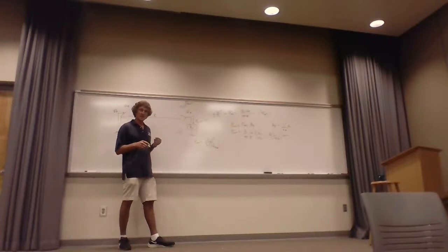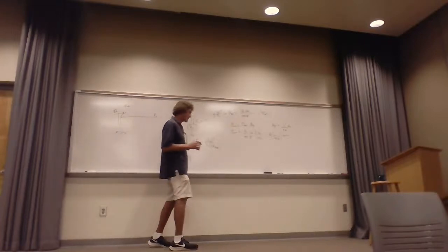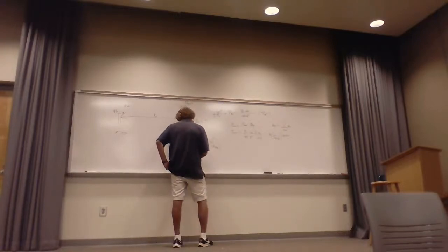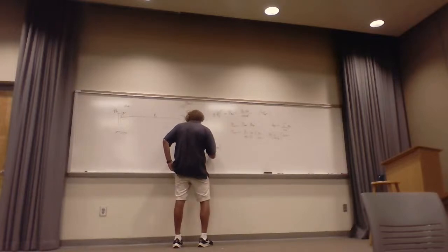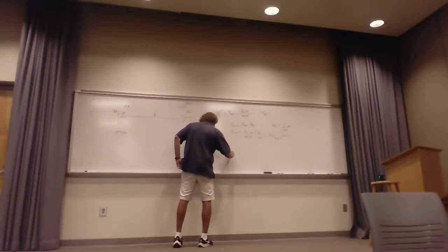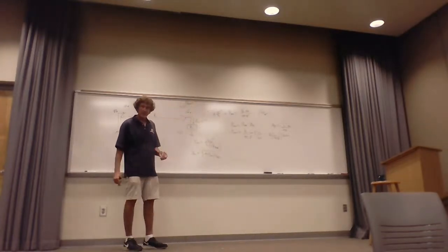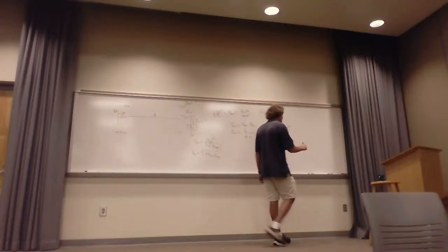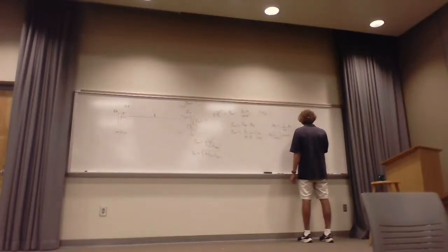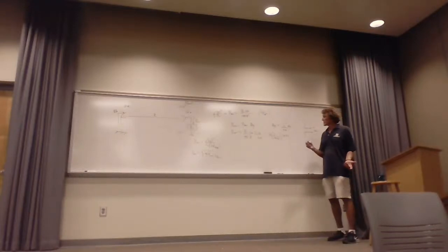If it's an open circuit, we get none of this power, but still there's the value that we use. So now that means V open circuit right here is equal to the square root of 4 times P received times R rad. Now that is something that's observable and measurable. If you take an antenna and cut off the load and measure just the open circuit voltage, you'll measure that. But remember, there's no power being received until current's drawn. If there's no current, there's no power. There's an open circuit voltage that is observable. Okay? Y'all with me on that?